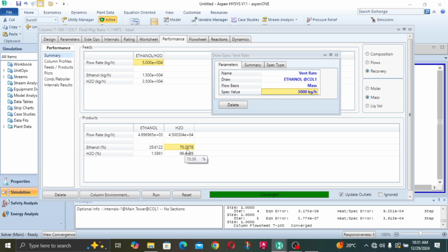But then we still have some quantity of H2O at the top. With the ethanol, it's predominant at the bottom and at the top, so it's not that good of a separation. That's why we said the column is one of the most complex equipment to deal with. It's painstaking operating it. It takes time, precision, research, and correct decision making. Let's go 15,000. So we have 95% and 10% at the top.